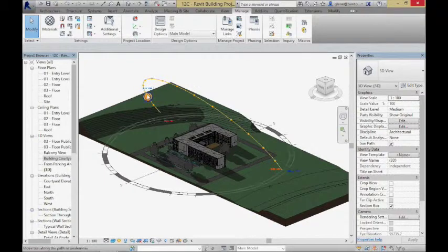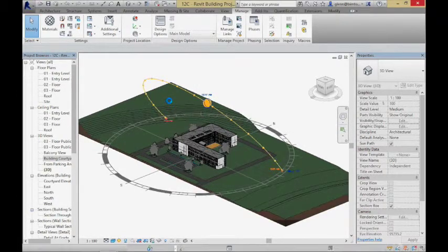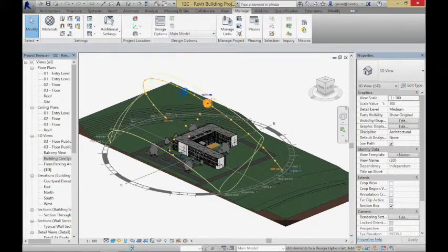I can change this by either dragging the sun or typing a time in there. So for example, if I want it to be 10 a.m., I'll put that in. And with a lot of redrawing, it'll move itself over there. You could also just drag the sun around in the sky if you want to. Although my machine's being slow, I can move it to some specific time. I'm just dragging the orb of the sun up closer to noon or 2 o'clock.